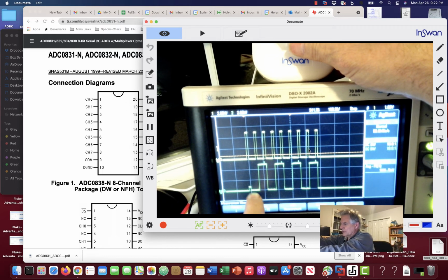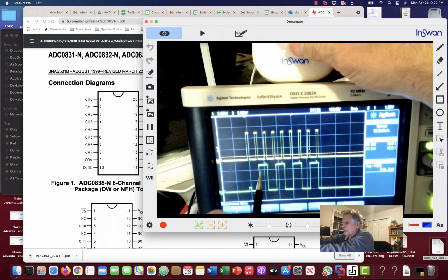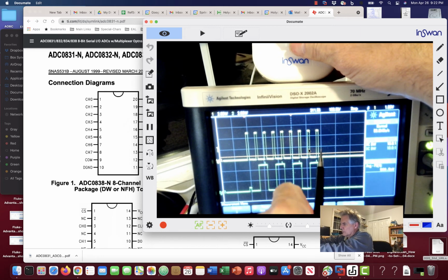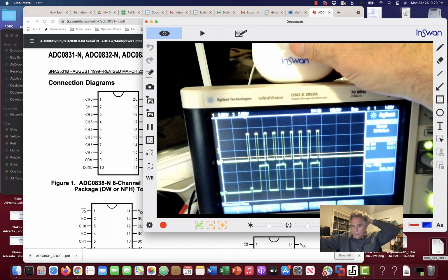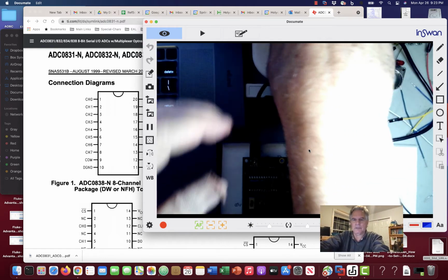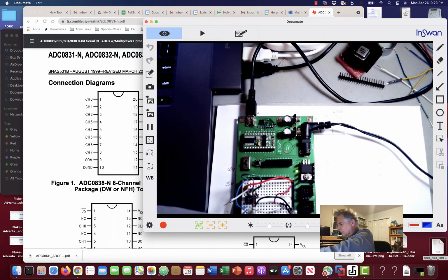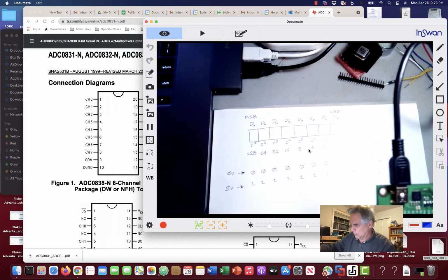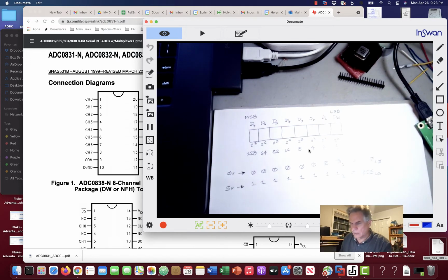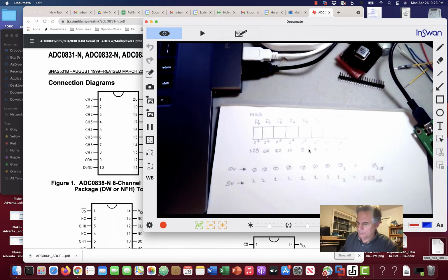Right after the first bit, that 0 is garbage. Okay? So that 0 is garbage, we ignore it. Then I got a 1 0, 1 0, 1 0 1 and then 0, because the sampling happens sometime after that last bit. So 1 0 1 0 1 0 1 0 in binary. All right. And just let Mr. Wizard move these things around here. Okay, yeah, this light gets a bit bright.